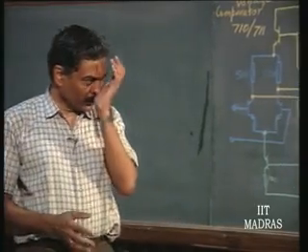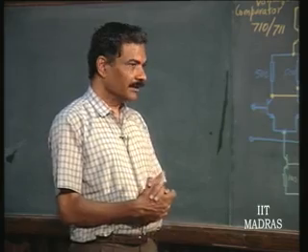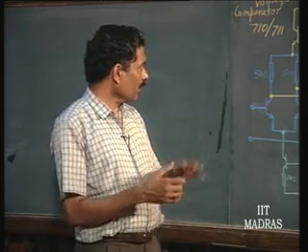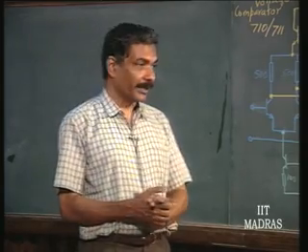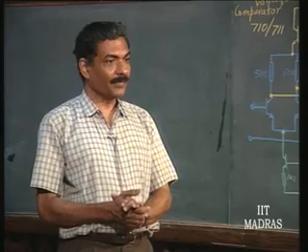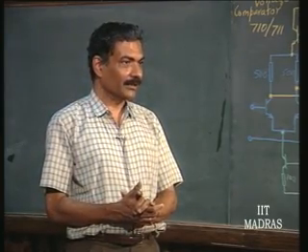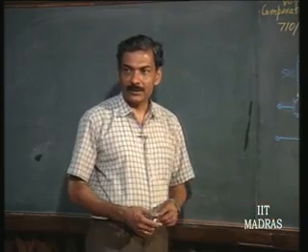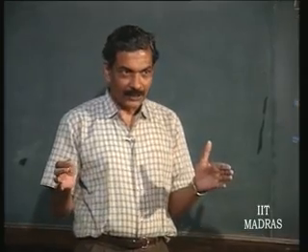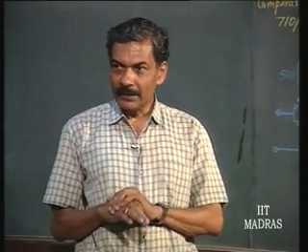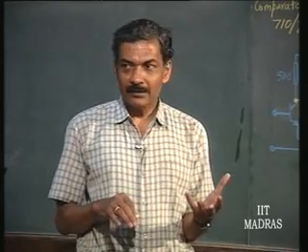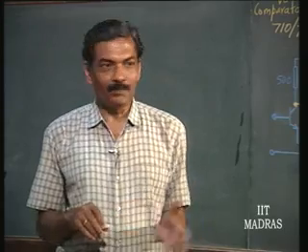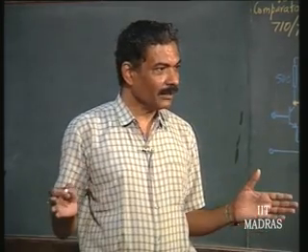Okay. So, now that we know the practical op amp, how its performance factors are fixed, what are the internal parameters which are to be chosen properly in order to design the op amp for a given specification, etc. We will discuss a variation of an op amp which is called a comparator. Now, there is always a tendency to use operational amplifiers which are used for negative feedback applications as comparators. Obviously, this is not good practice, okay, because when the application is comparison of voltages and there is not likely to be any negative feedback, we have already understood that there is no problem of frequency instability arising, and therefore, there is no need to compensate. And if we do not compensate, we have the widest possible bandwidth of usage.